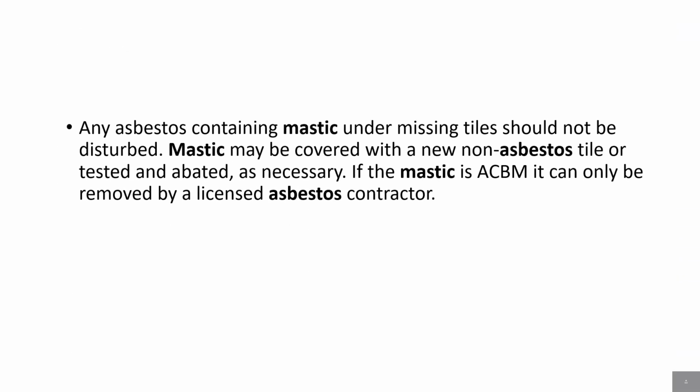Any asbestos-containing mastic under missing tiles should not be disturbed. Mastic may be covered with a new non-asbestos tile or tested and abated as necessary. If the mastic is ACBM, it can only be removed by a licensed asbestos contractor.